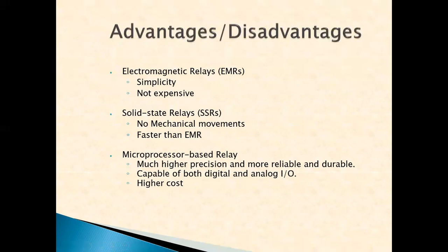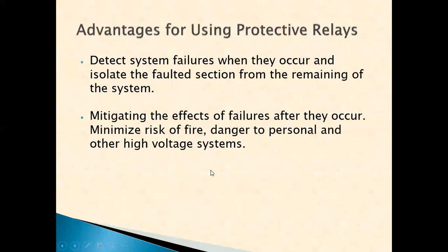Advantages of relays: electromagnetic relays are simple and not expensive. Second one, solid state relay has no mechanical movements and is faster than electromagnetic relays. Then microprocessor based relay has much higher precision and is more reliable and durable. It is capable of both digital and analog input output, but its disadvantage is that it has higher cost.